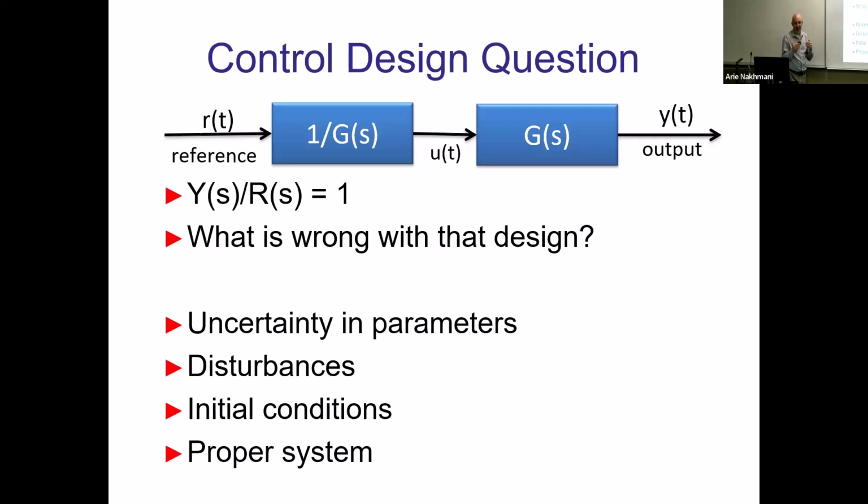Which means the derivative that you use in these transfer functions is not a causal function physically. You cannot actually implement it. So you do not have transfer functions where you have more zeros than poles, which is non-causal, because you need future values to compute the output of the transfer function. So you physically cannot build it. You cannot build that controller if it is that way.